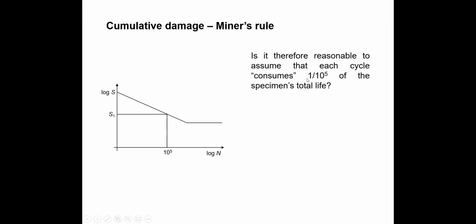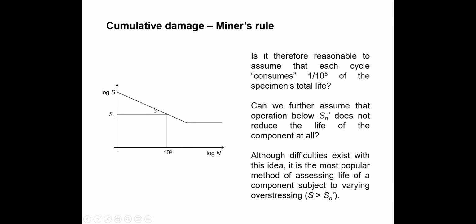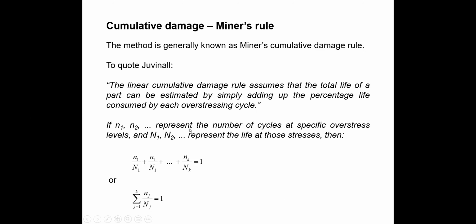So yeah, as I told you, if we apply one cycle with this stress range, it will consume 1 upon 10 to the power 5 of the lifetime of this specimen. But it does not affect below the Sn prime range. If you apply that, it does not affect the specimen lifetime. It will not reduce the lifetime. Okay. So when we do the calculation with the Miner rule,